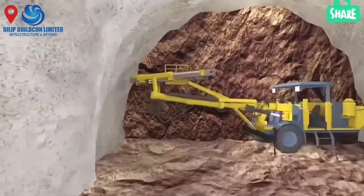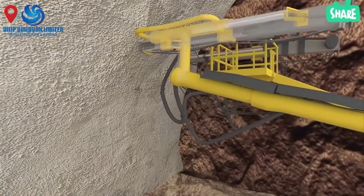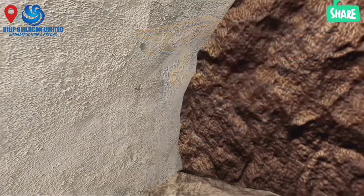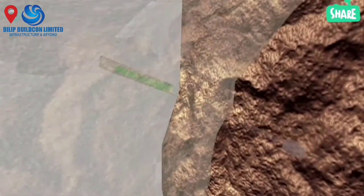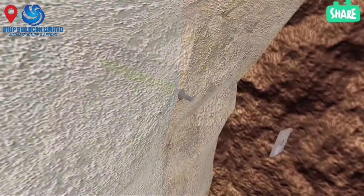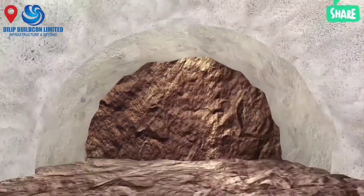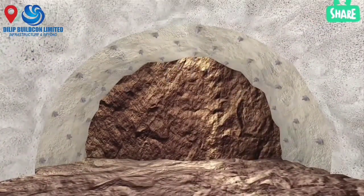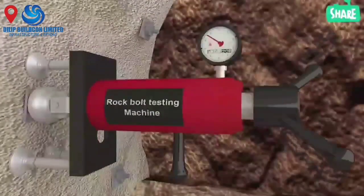Rock bolt drilling and grouting is done as per the rock bolt design given by geologists. Depending on rock class, plates are fixed and bolted and a predefined amount of torque is applied. Rock bolts are then tested for load-bearing capacity after 15 days.